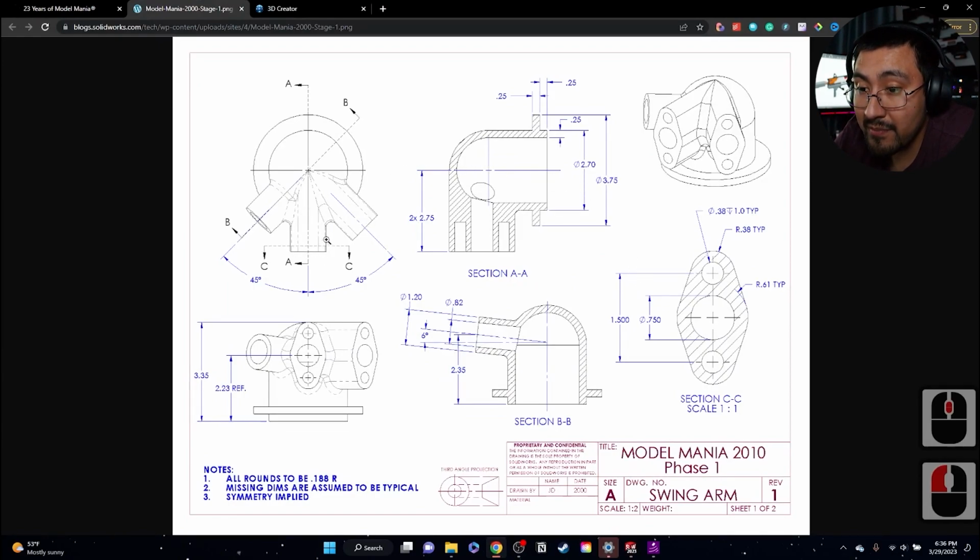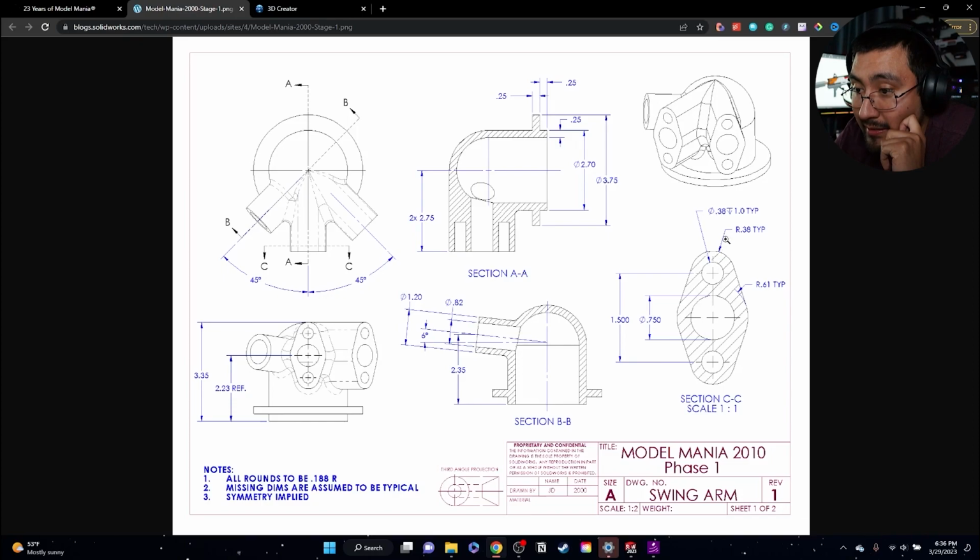Now the next step is I'm going to make this next pillar. Or sorry, the next manifold exit or opening or outlet. I'm looking for any dimensions that call out any difference in this. And I doubt that. So I'm going to go ahead and assume these are exactly the same, and all it is is a 45-degree turn. Now, I'm not going to redraw this. What I'm actually going to do is a circular pattern and only do it by 45 degrees. So I'll show you guys how to do that.